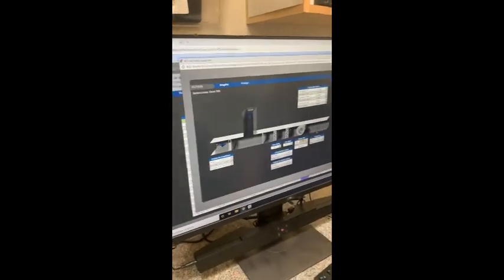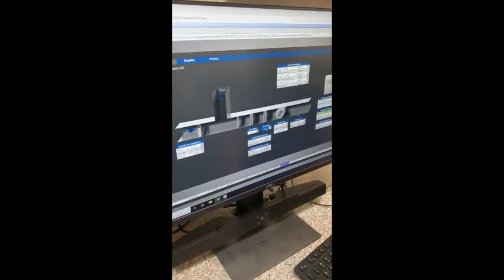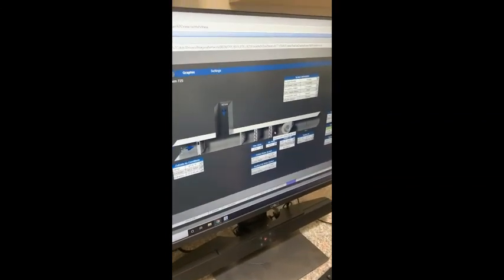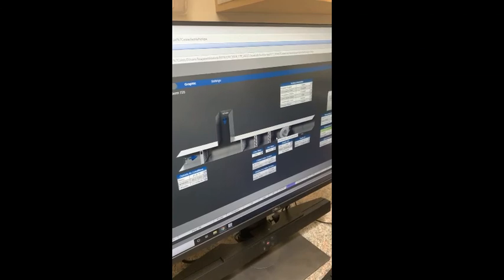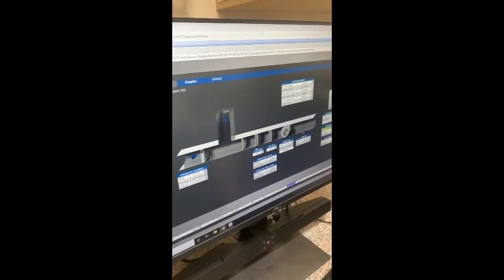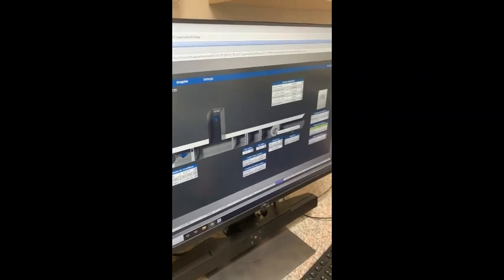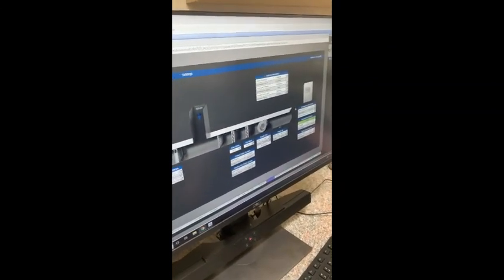You will see as the valve opens, like this one here, there's a little bit of red, and it will scale up. It only goes up in quarter increments. Same with the chilled water. The fan will turn, and the fan status is showing. Again, we actually do read status. Yeah, we talked about that.